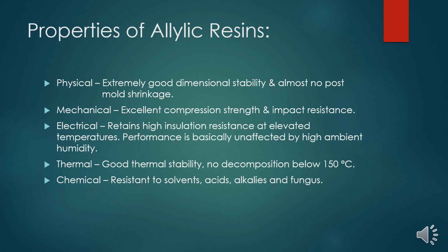Allylic resins are high-performance thermoset materials. Some physical properties of this resin is that they have extremely good dimensional stability and almost no post-mold shrinkage. Some mechanical properties are excellent compression strength and impact resistance.